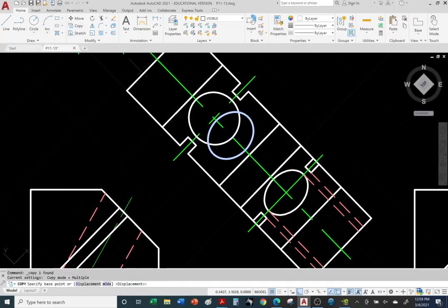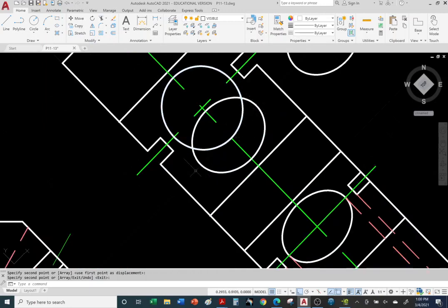Make a copy. I'm going to grab it by its center and slide it with respect to our axis. Slide it in the X direction. Click. You can keep clicking to make another copy. All I need is one. Okay, so I'm going to trim this one. So remember the trim command? So I'm going to remove the bottom portion of this ellipse and keep the top portion.